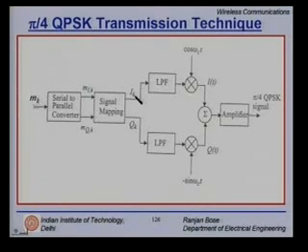But once you have this I_k and Q_k, you low pass filter it, and then you have the in phase cos omega_c t or cos 2 pi f_c t and sin omega_c t with a negative sign. You get the in phase component and the quadrature, add them up, amplify and shoot it off.